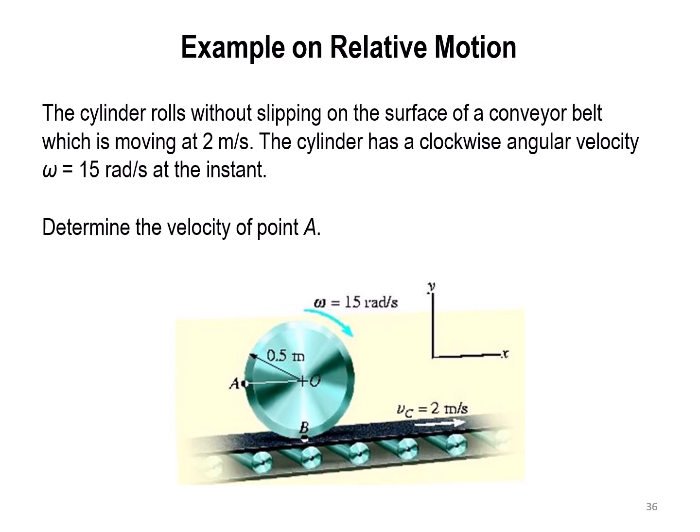Just remember once again that we have non-slipping. That means the velocity at A can be found simply by making the rotation around the point B. So we need to sketch a line from B to A. That will be my link. And that link multiplied by omega will give me the velocity at A.